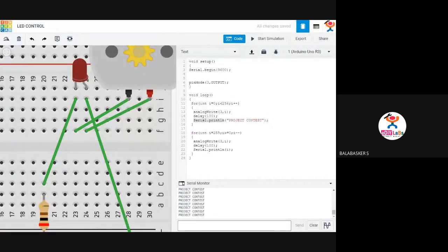Angeline, is that okay? Do we specifically have to give 9600? Yes, ma'am, because that is the basic requirement of 9600. When you are going for high speed devices, that baud rate varies. Actually, there are n number of baud rates. For example, 9600 and multiples of 9600, 17,000, 20,000, 30,000, up to 3 lakh bits we can transmit per second. So in order to understand in a simple way and for a basic level of communication, 9600 baud rate is quite enough.